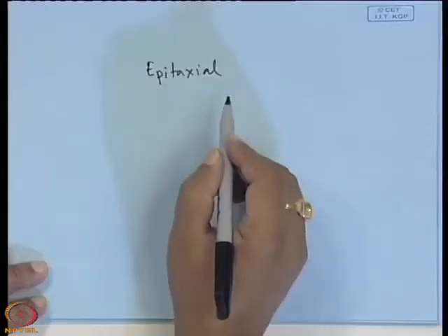That kind of precise doping concentration and precise thickness is not possible in case of bulk crystal. Epitaxy means a single crystal layer, a very thin layer of some nanometers, some angstroms, 100 angstrom, 200 angstrom, 400 angstroms, right.